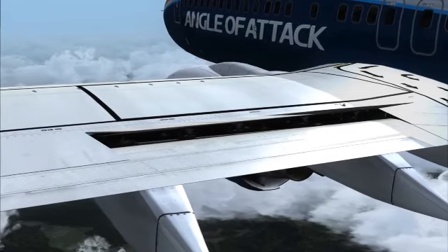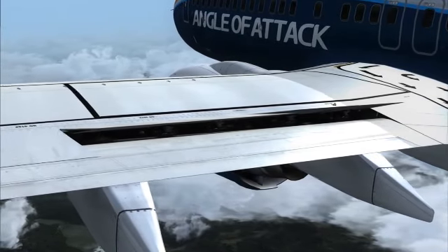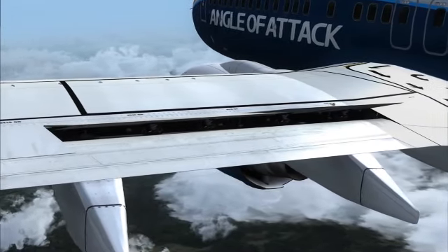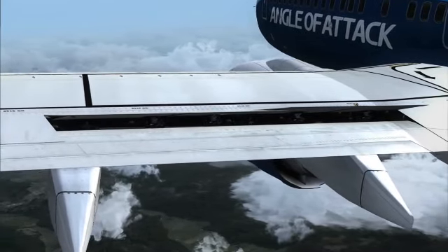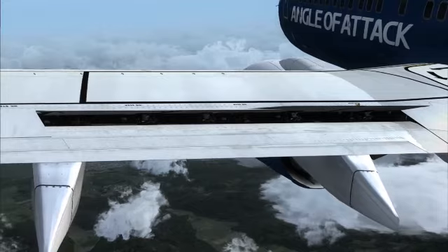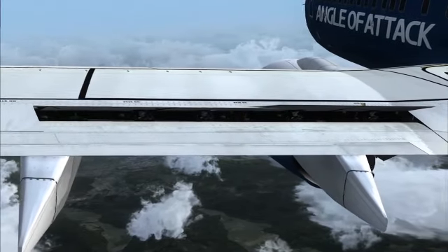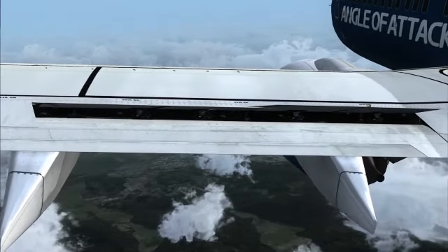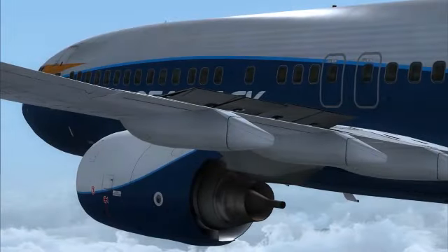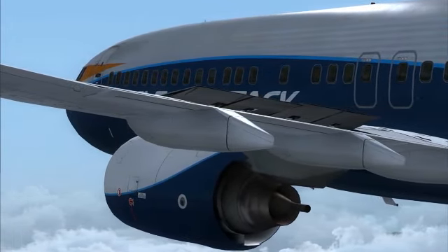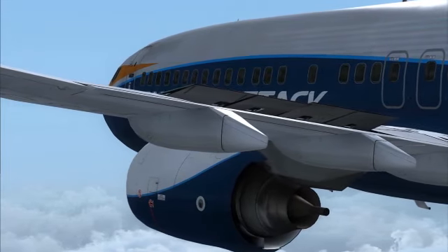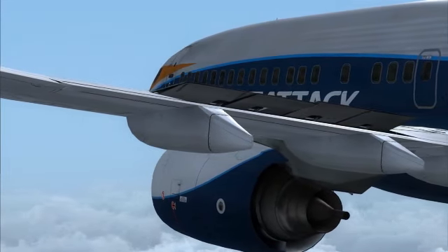During flight, they can be used in one of two ways: to aid roll control by providing significantly higher roll rates through uneven extension of all spoilers, a feature discussed more in depth in the primary flight controls lesson; or to allow for steeper rates of descent without a significant increase in airspeed. It's not uncommon to find airliners using flight spoilers to increase their descent rate.